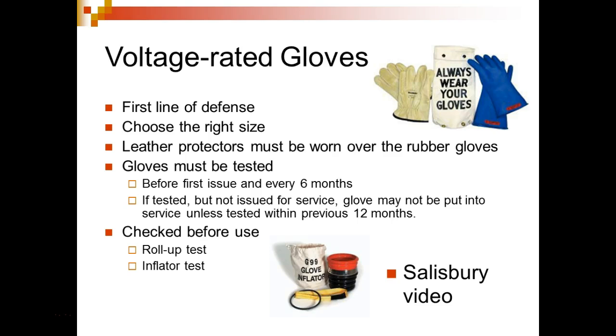And then after that, the motors usually burn up. Sometimes you get lucky, but odds are if you smelled it, it's not producing the horsepower it's supposed to, because odds are it's got shorted windings in it.